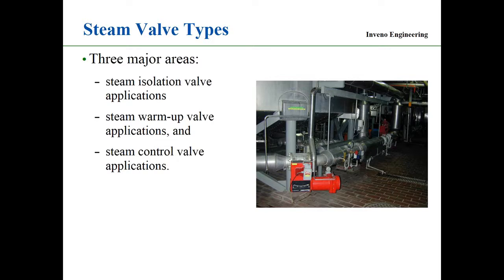Another one that's big in the steam system is steam warm-up valves. So any valve that's 3 inch or larger, we have to have a steam warm-up valve to warm up the system slowly. So we want to make sure that when we shut the main isolation valve, the warm-up valve is also in the off position and not leaking through. So we want to test the warm-up valve.